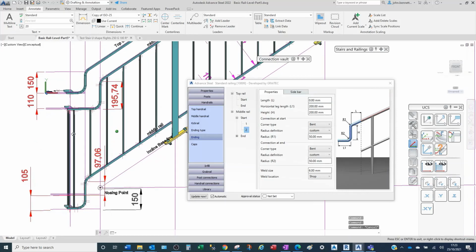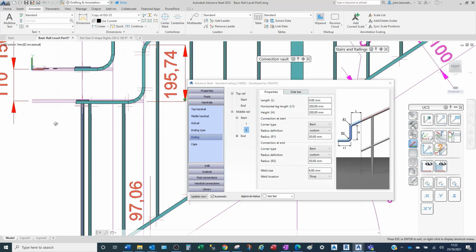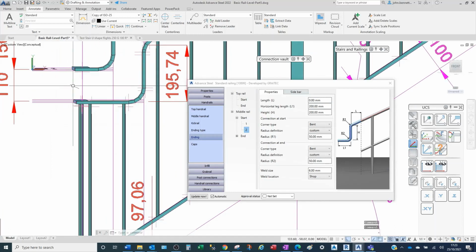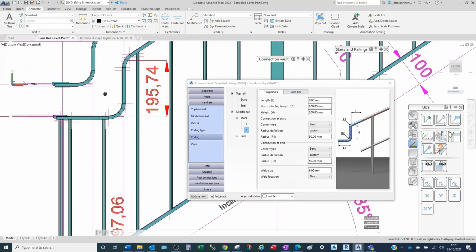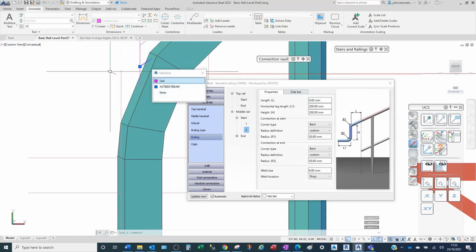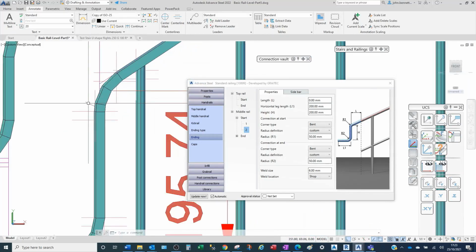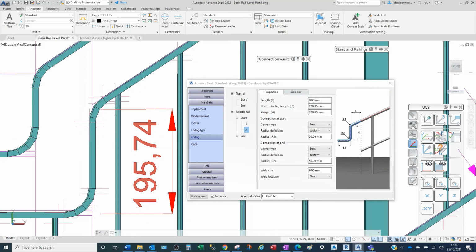So this effectively gives you the horizontal setting out, and then obviously, as I said earlier on, you need to start looking at the vertical setting out. Now obviously we want to achieve 100 millimeters in here, the same as we have done elsewhere. But what happens is, as the angle of the rail changes, normally from the staircase, this point will actually move and adjust. So if you were to change the angle of the stair, the actual intersection point would change there.